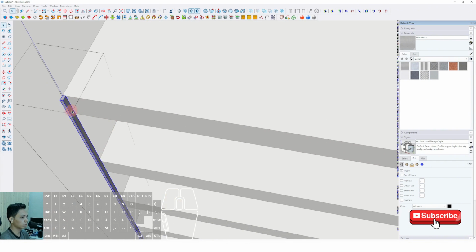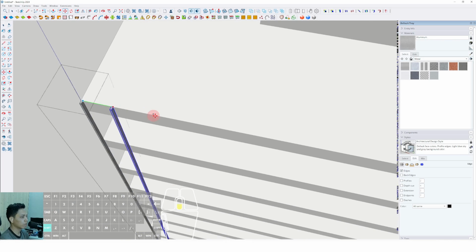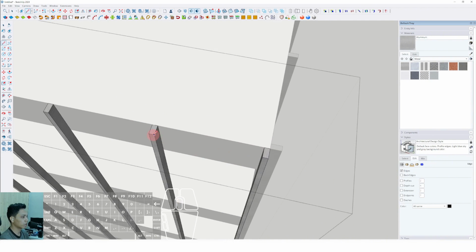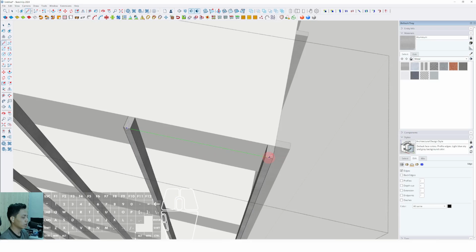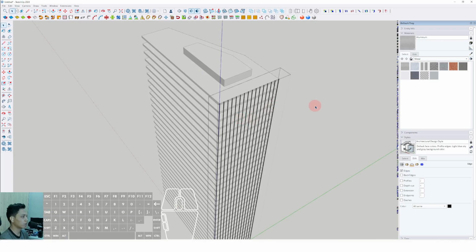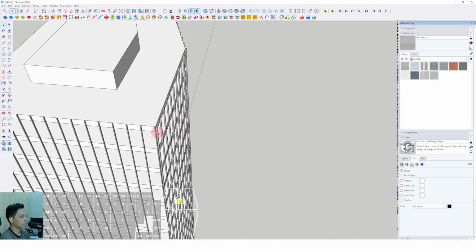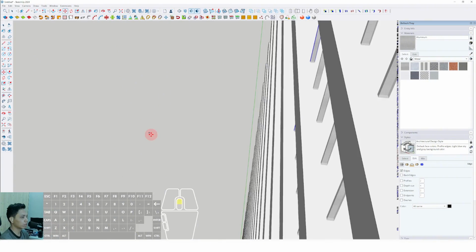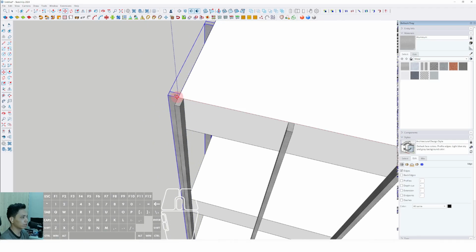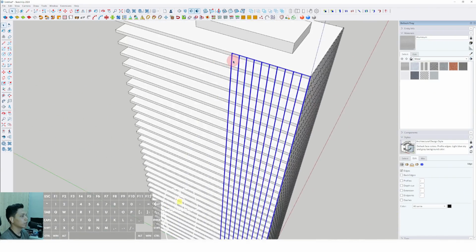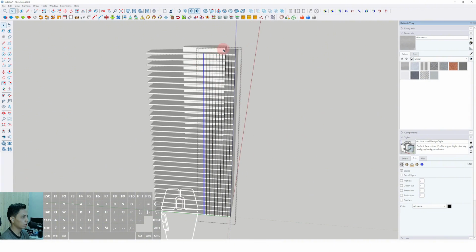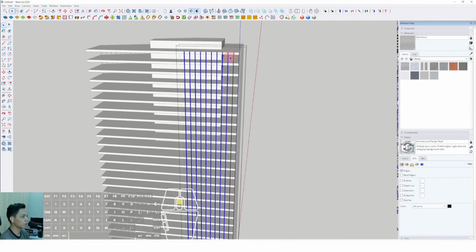Then we can type 15, value 15 slash enter. I mean, it was similar with the first vertical arrangement. Okay, approximately just like this. Then we can continue to select move, press Ctrl, then place to this position, and just continue to duplicate this vertical frame to the another side of the empty building side over there.